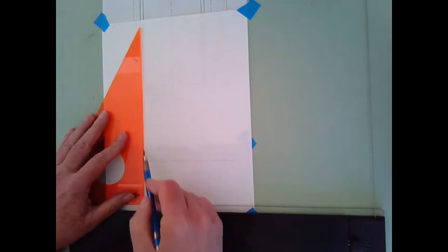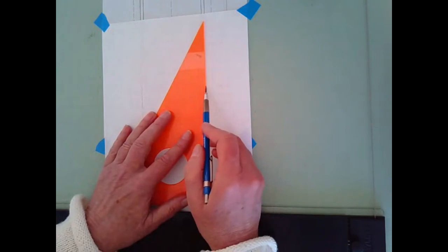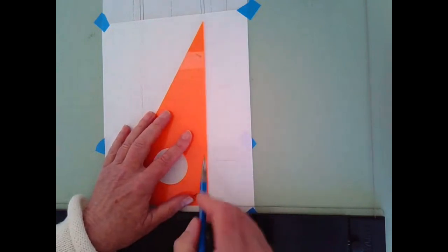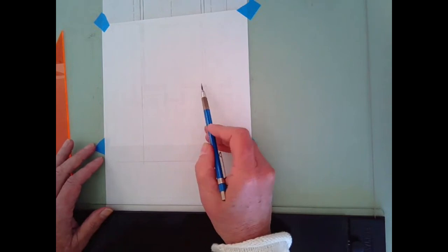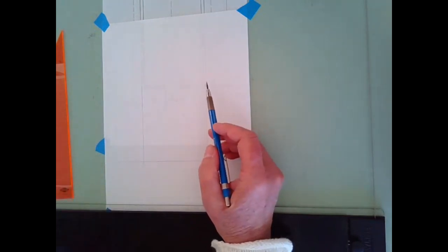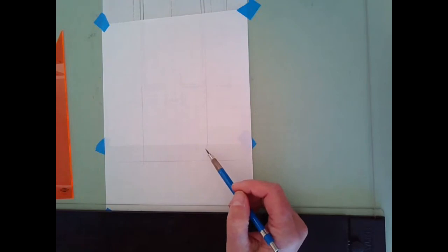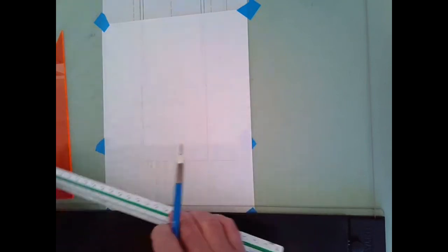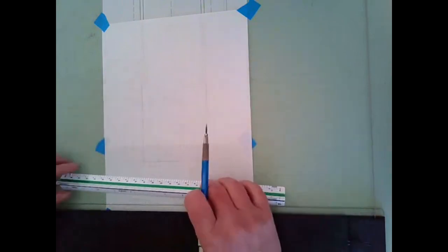So I'm going to pull the outside wall down on both sides. Would I take this line, the line inside the inside wall? Would I project that down? And why not? Leona says no, and so why would I not project that down? It's interior, you don't see it. So I'm only taking what I see from the outside, which is its outside lines.